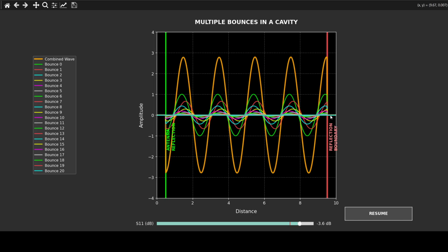But at the same time, the power, which is V squared over R, is reducing because you are increasing R. Basically, we have a theorem, the maximum power transfer, which concludes that if you want the maximum power to be transmitted from a source with impedance of Rs, your receiver also needs to have the same impedance. So that's another important factor here.